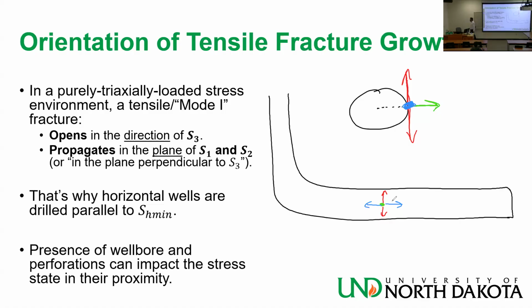Just bear in mind the well may not be in the direction of the z-axis. It might be the direction of the x-axis, or the y-axis. So you may not call the axial stress sigma zz. You may call it sigma xx, or sigma yy, or sigma ii, where i can be variable. But as long as it's a normal stress with the same letter for the subscript, you are good.